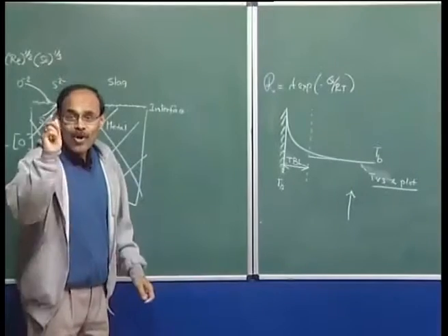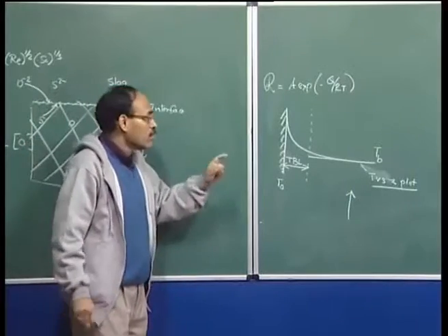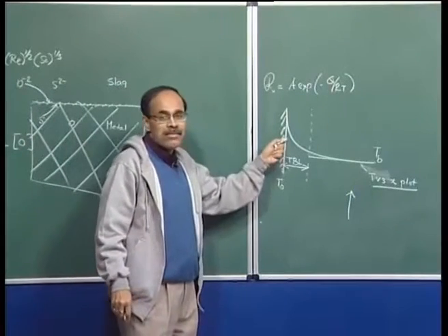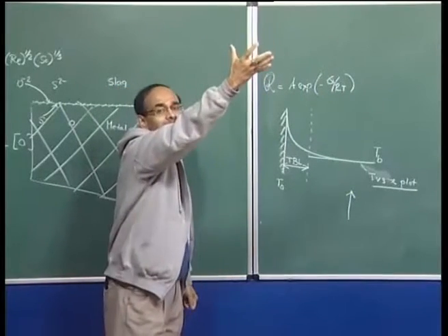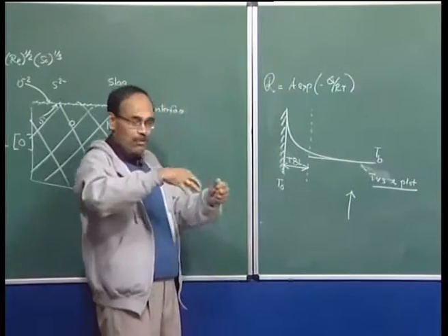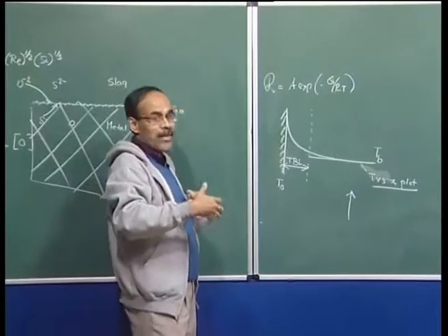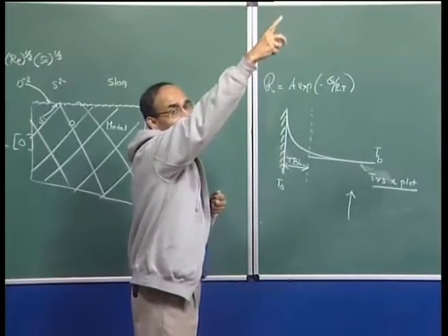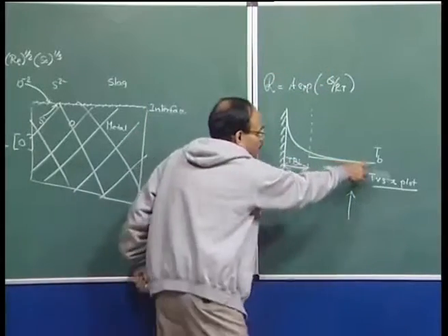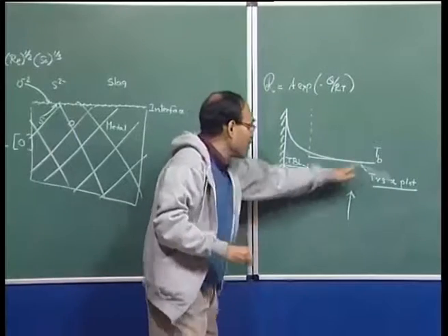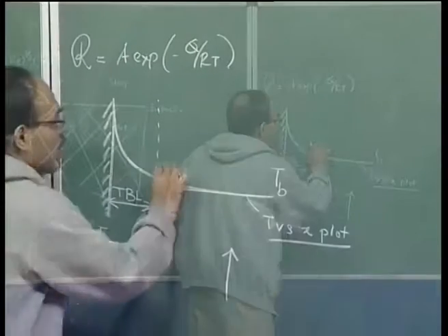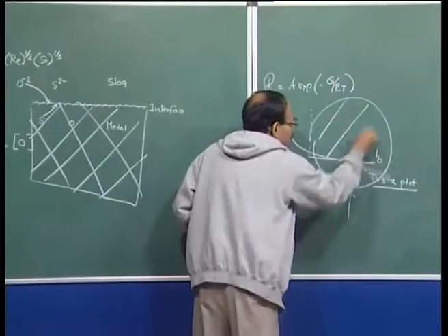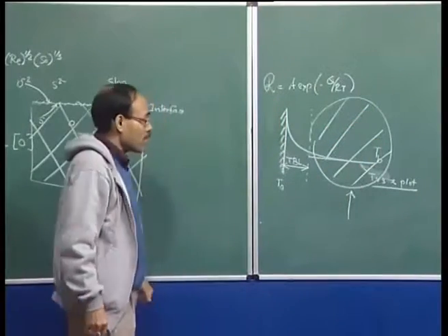That is why, if you remember, when you determine the rate of the process, you may have used the temperature far away from the interface. That is the bulk temperature, and the driving force for temperature is the difference between the surface temperature and a temperature which is far away from the solid surface. This temperature actually prevails up to the edge of the boundary layer, because of the simple fact that we have made an assumption that the transport of heat within the bulk is instantaneous, and that there is no temperature gradient.